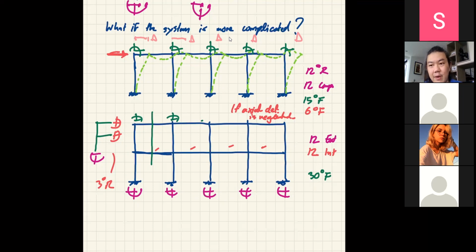That would be 12 because you now have 2 floor levels. So you need to have 1 horizontal displacement for each floor. Very good. With 12, you almost got it. It just slipped through your fingers like that. So here, yes, it's going to be 12 degrees of freedom if axial deformation is neglected. Okay, very important. So any questions, folks?